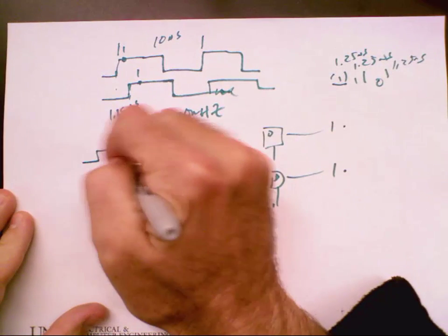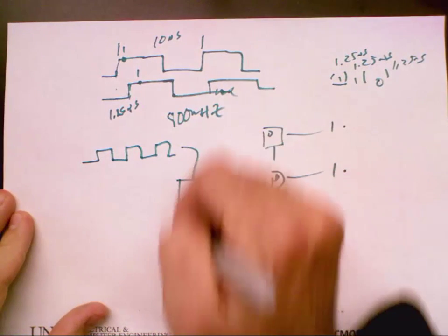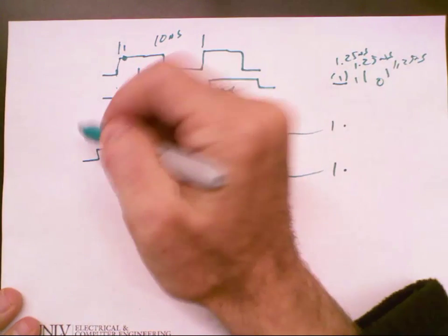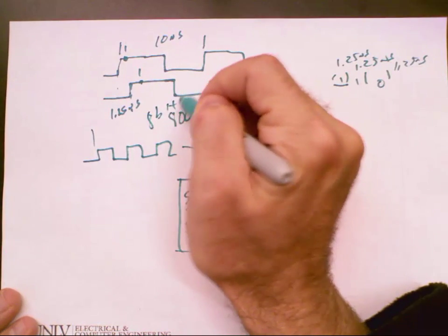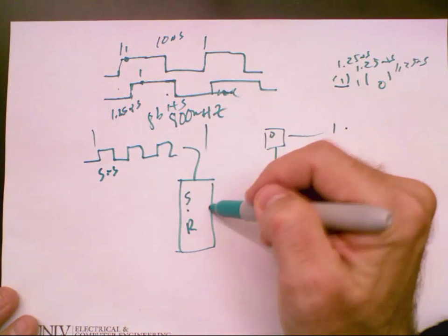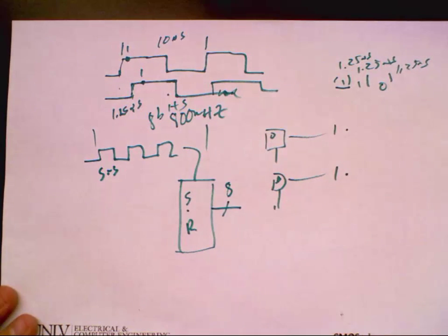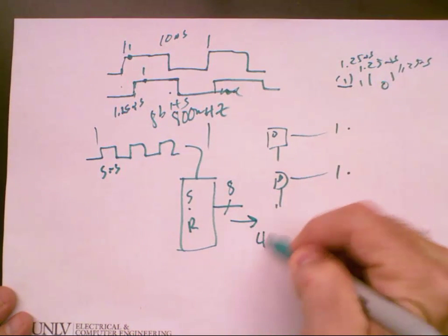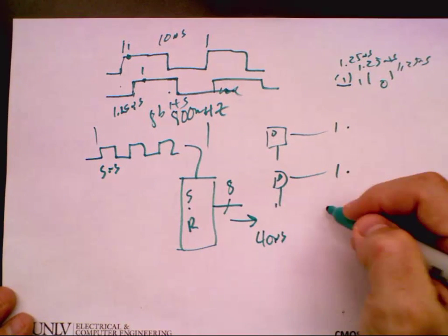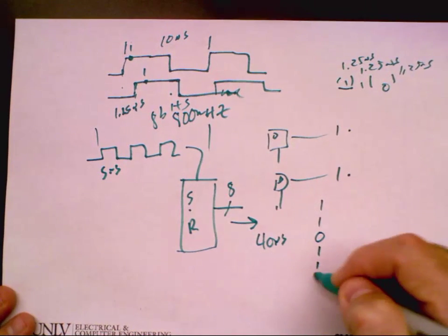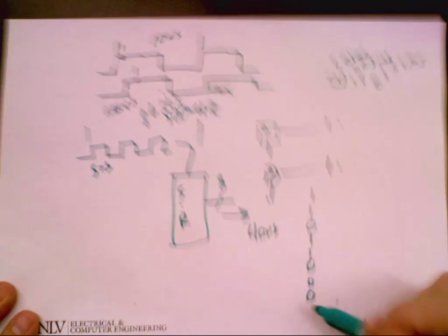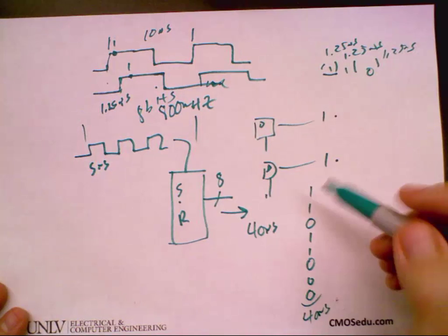Let's say that I have this string right here, right? And I go into a shift register. Okay, and let's just say I clock in 8 bits. And each bit's width is 5 nanoseconds. After I've stored the 8 bits in the shift register, after 40 nanoseconds, I chunk out the 8-bit word. Does everybody see that? Okay, I look at the word, whatever it is, 11011000.